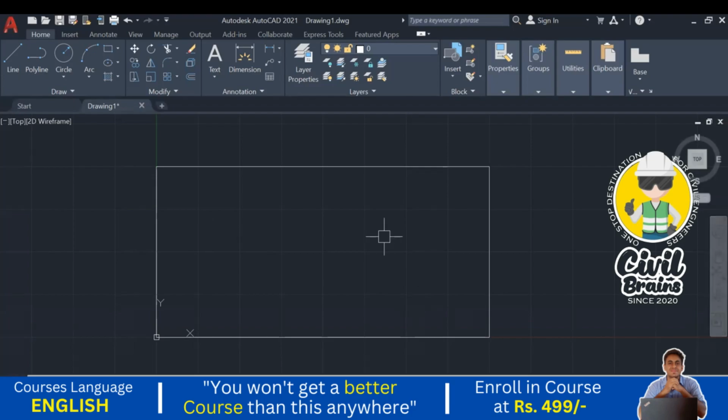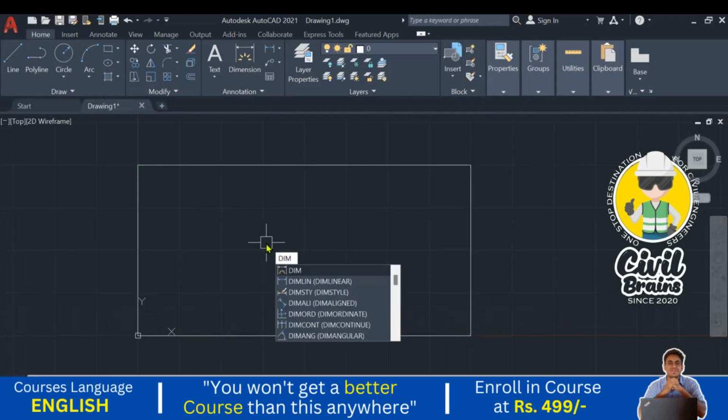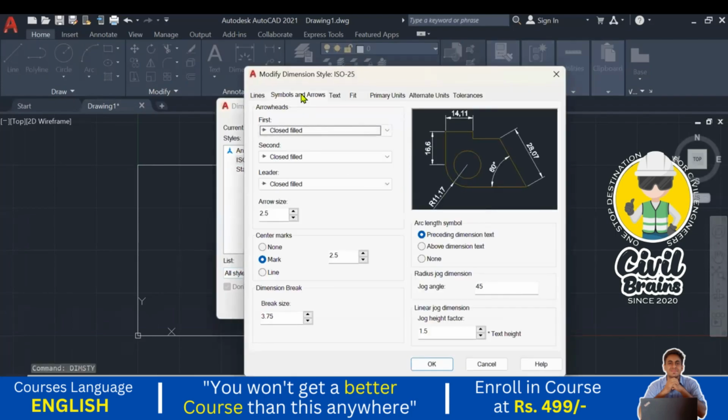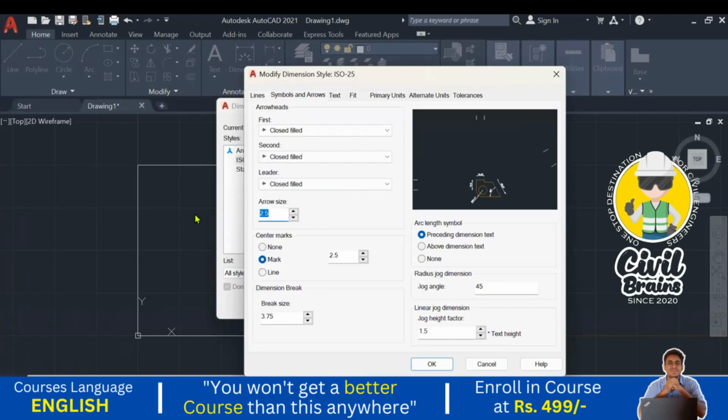Before that, after setting the limits, what is the next procedure? We need to set the dimensions. Go to Modify. I set all the lines, everything, to 100 so that it will be set properly. For the arrow I take 150, a little bigger size. This one we can consider 100, and this one also 100.